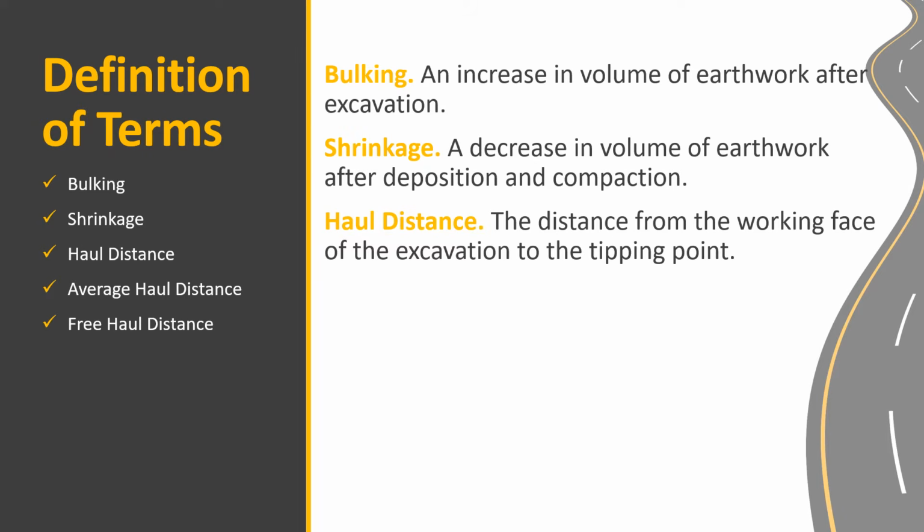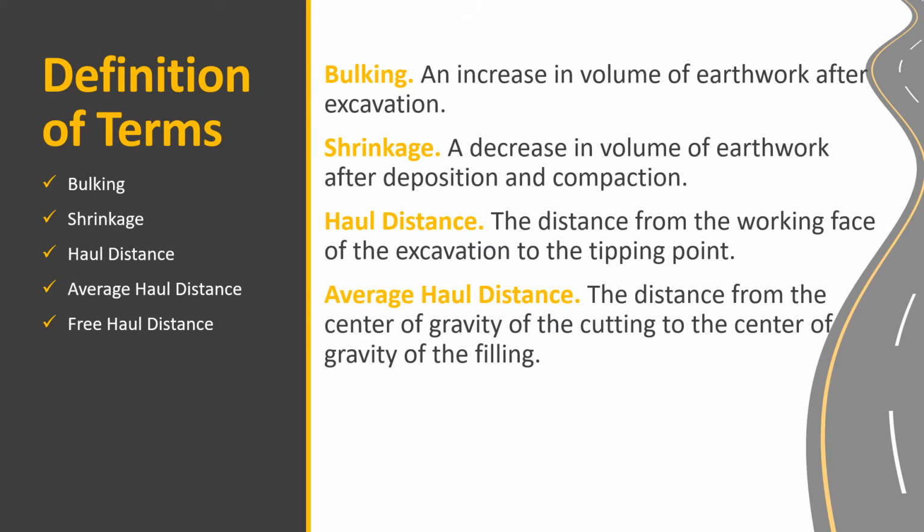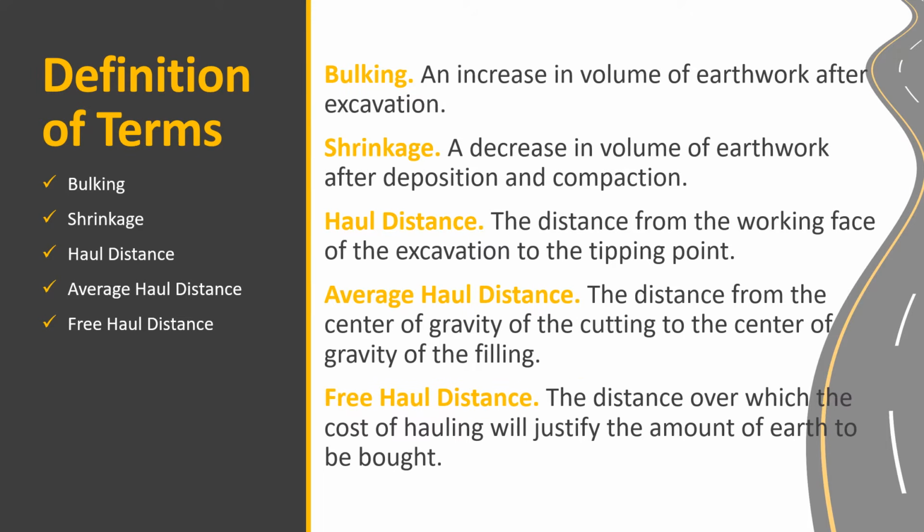Haul distance is the distance from the working face of the excavation to the tipping point. So it is the distance where you haul or you get soil from a source to the tipping point, yung paglalagyan ng soil. Average haul distance is the distance from the center of gravity of the cutting to the center of gravity of the filling. Free haul distance is the distance over which the cost of hauling will justify the amount of earth to be bought.